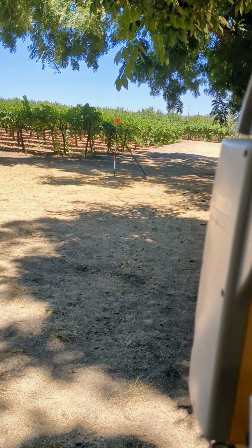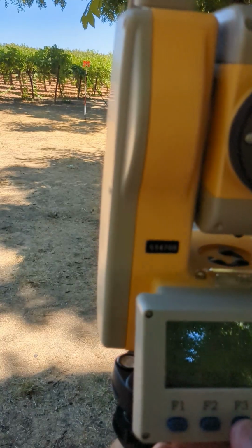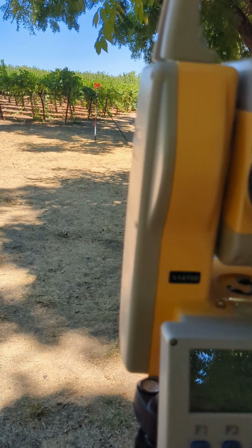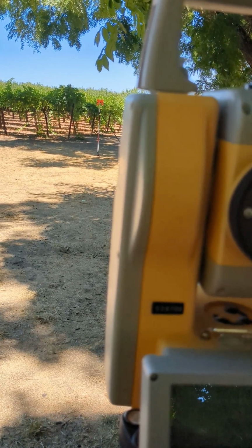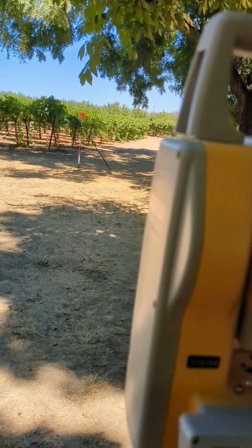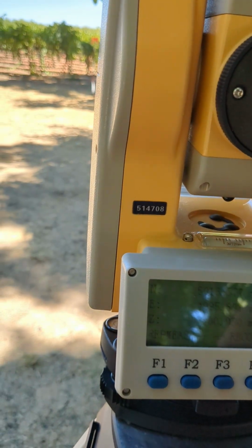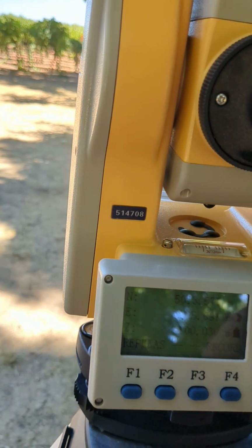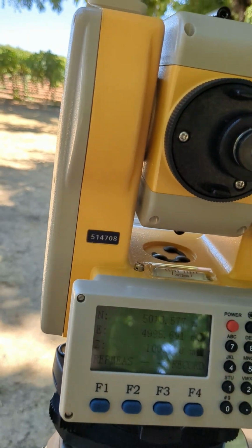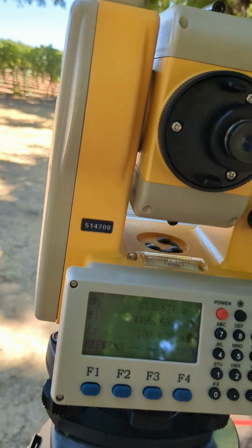Okay, I have lined up through the lens the target, and I have an option here to take a measurement. I'll press my measure, and it'll go and see a signal strength and display a measurement. It continues to make measurements. You can hear it clicking, but I'm going to press the stop button to save the energy. And here I can see that I'm 5,013 meters northern and 4995 something eastern. So I'm 13 meters one direction and 5 meters approximately the other direction. And that makes about sense in terms of where my data was.